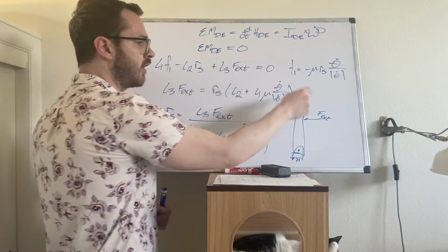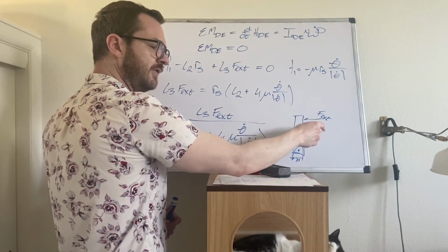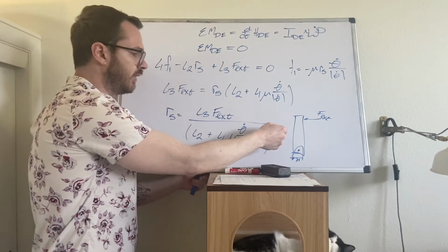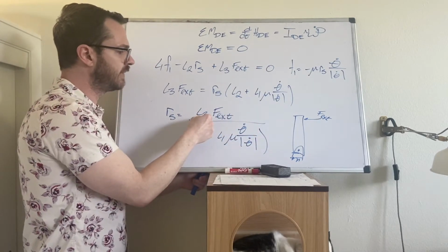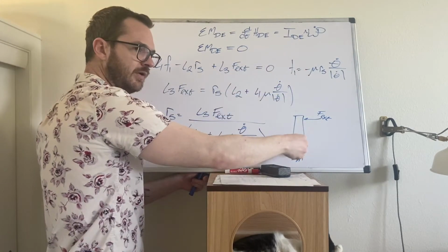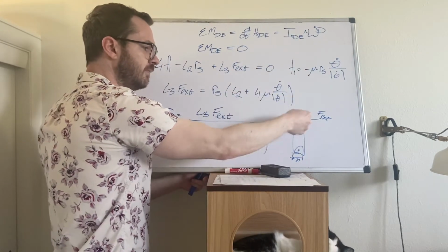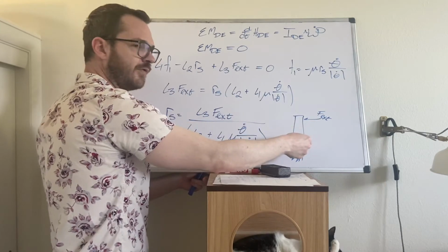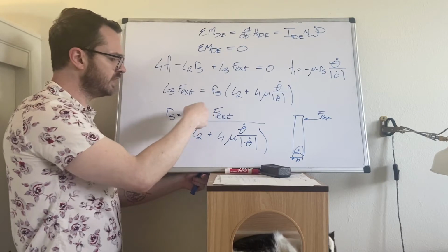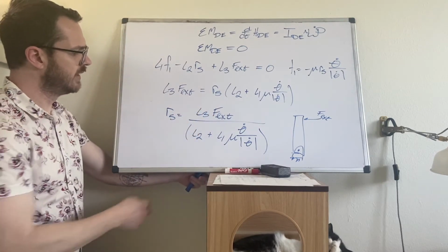Clearly the harder you push against this pendulum, the greater the reaction force at that contact point. It's linear with respect to F external. Similarly, what if the lever becomes very long, or the location of the applied force changes? Then your moment arm is going to change, so it's linear with respect to that as well.